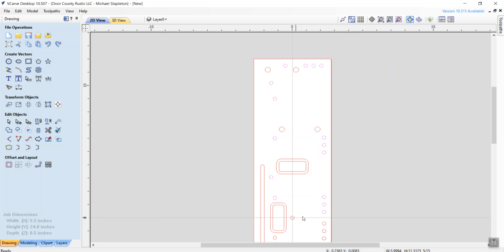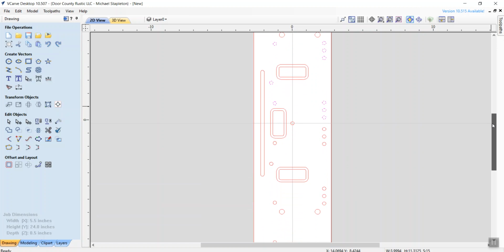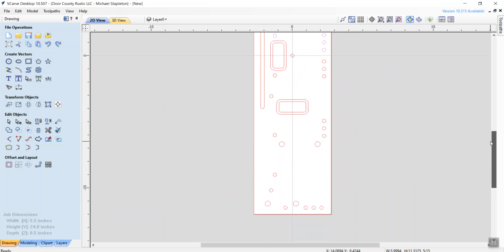I remember I already did the center pin, so now I'm going to let go of the shift key with my left finger, and I'm going to use the scroll bar to scroll down to the bottom half. I'm going to put my left finger on shift, so that shift key is held down. Now when I drag here, I'm continuing to select. I'm going to click on that one, select, click, select. And as long as I stay low here to avoid that 3/8 inch hole, I selected that. So again, all of these 1/4 inch ones are all selected.